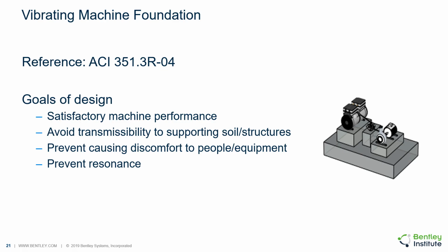Next, we move on to vibrating machine foundations. STAAD Foundation Advanced can be used to design foundations for vibrating machinery as per ACI 351.3R-04 guidelines. The basic goal of designing a machine foundation is to keep the vibration amplitudes within certain limits to